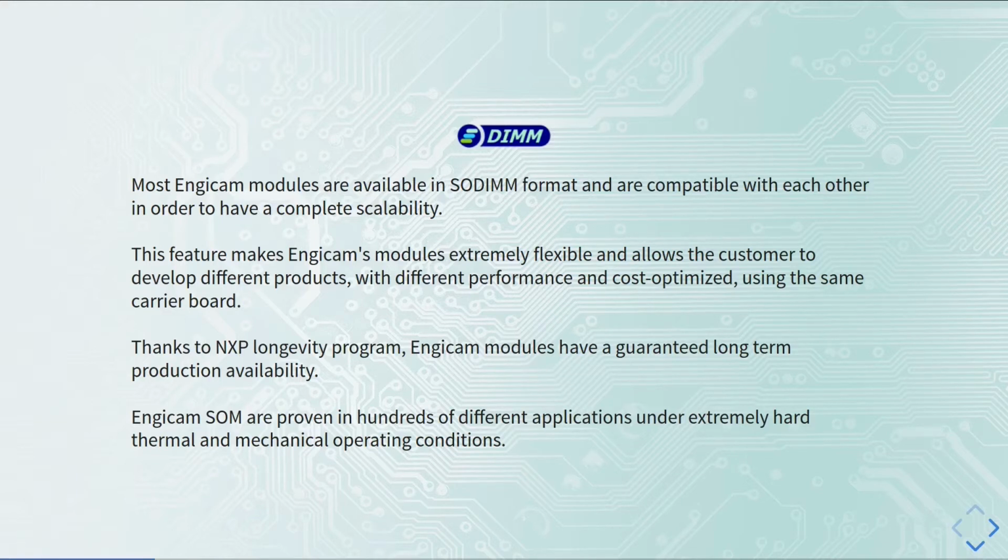But Engicam created this internal standard for this product that makes a further step of compatibility, because all the modules that follow the EDIM also have a specific configuration in the system on module pin output. This means that if you have two different modules that are both EDIM modules, you can plug them in the same board without any change from a software point of view.